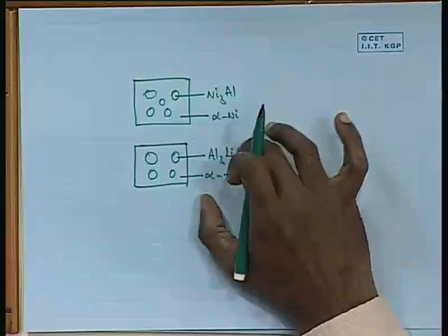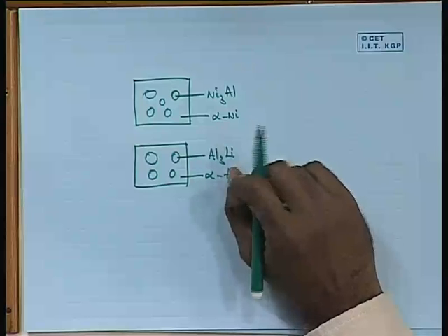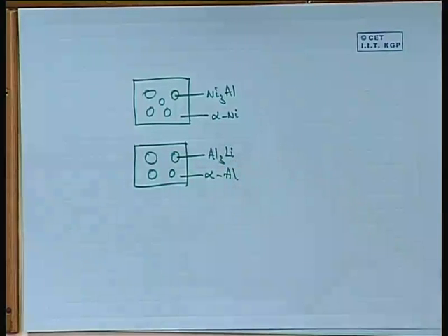So that is why, in fact, I will show you a little later why in one particular system we want to convert a tetragonal precipitate into a cubic precipitate to improve the strength and ductility of the alloy. We will come to that a little later. So, this Al3Li alloy seems to be very good, but ended up into some problems.